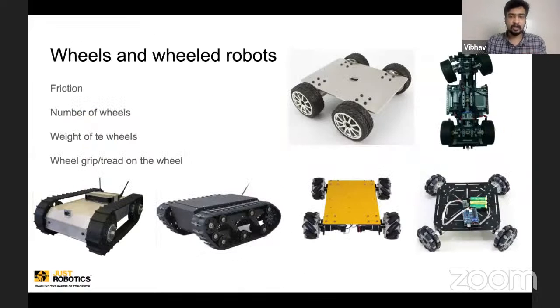With a wheeled robot, one rotation of the motor will result in one full walk cycle, so it is more efficient, and it is easier to construct. The control system and the number of motors, linkages, moving parts are less. You just have to put the motors and the wheels together and have one chassis, then you will get it.